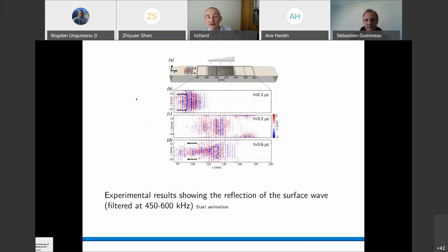Now, what about experiments? In the world of ultrasonics, you can excite an almost perfect Rayleigh wave. This is how non-destructive evaluation, or crack detection on surfaces, is done. Industrially, this subject is very widely used. If people want to look at the structural integrity of an aeroplane or an oil refinery, they will be sending Rayleigh waves or flexural plate waves up and down and through the structure and looking at the reflection. So exciting a perfect Rayleigh wave is something these people do on a daily basis.